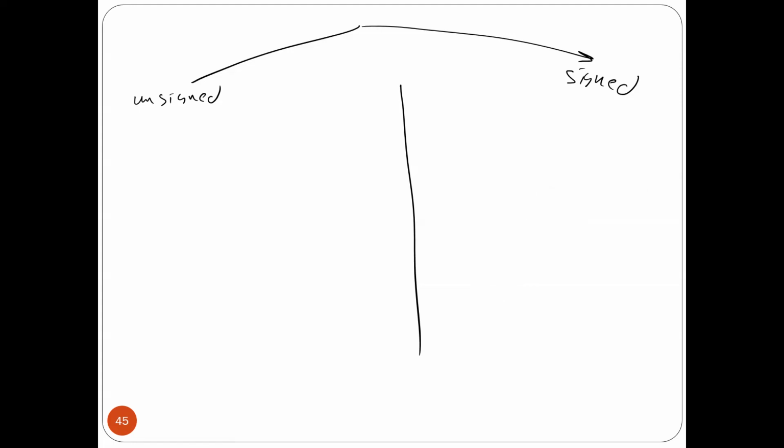Anyway, now I'm going to explain how you can tell if there is overflow or not. In the case of unsigned numbers, if I add the numbers, for example, something like that, normal addition: 0 plus 1 is 1, 1 plus 1 is 0 and we have 1 here. 1 plus 0 plus 1 is 0 and we have 1 here. 1 plus 1 plus 1 is 1, and then we have a carry here. Very easy, very simple.